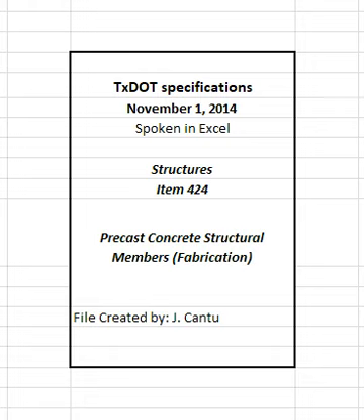Shade the concrete during casting if necessary. Use an approved retarder, in accordance with the manufacturer's recommendations, when the air temperature is above 85 degrees Fahrenheit if necessary to control concrete slump loss and lengthen the time for placing, consolidating, and finishing operations.